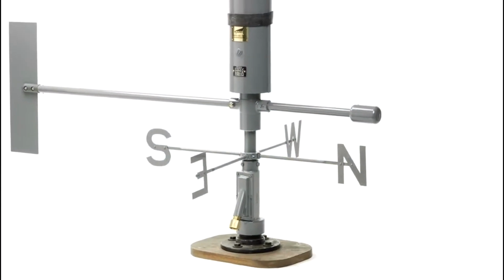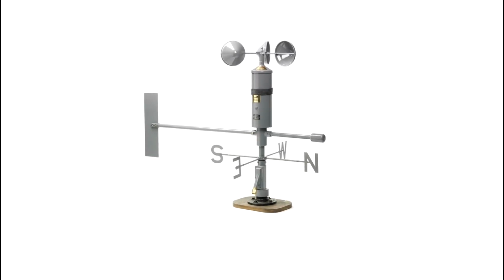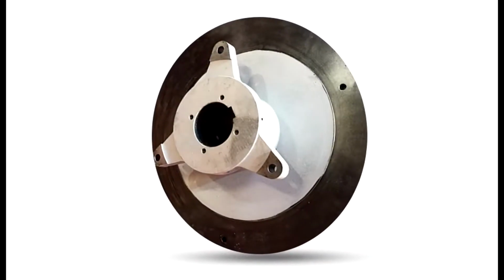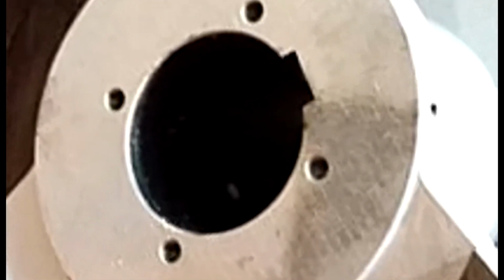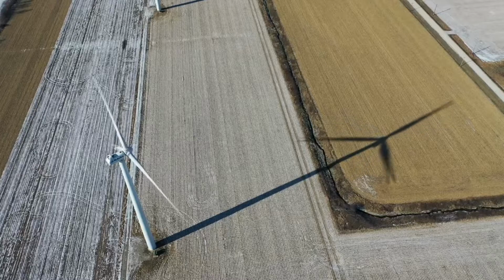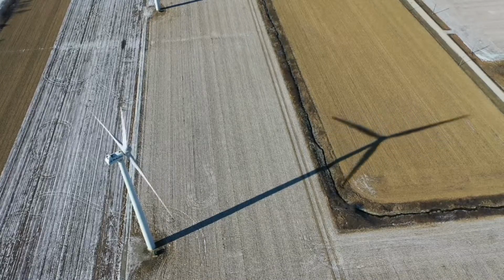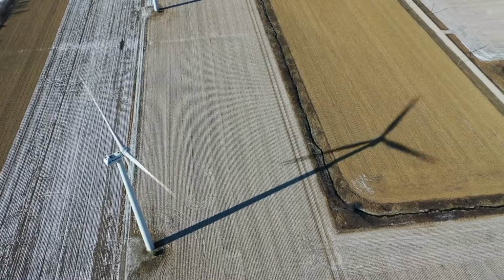Wind speed is measured by an anemometer, which transfers the data to the controller. The brake stops the rotor mechanically, electrically, or hydraulically during emergencies. If there is no wind or decrease in wind force, the blades will move slowly and electricity will not be produced.